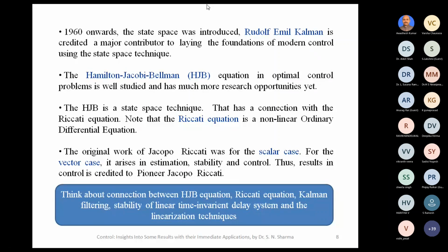The Riccati equation is for regulator design, LQR. But the Riccati equation has its origin in the Hamilton-Jacobi-Bellman equation, with a quadratic performance measure and a linear system. It may be time invariant or time varying. Then in feedback design, the regulator means feedback parameters. Regulator design means parameter design. The feedback parameters evolve and obey a certain rule. In that case, it is a Riccati equation.